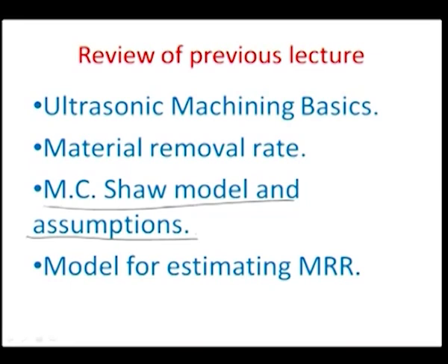And also that the indentation created by this grain would produce a crater on the surface, and for all practical purposes we should consider the amplitude of motion of the tool head to be constant, and so forth. So there were a set of assumptions that we had made for predicting the MRR or material removal rate, and then we started modeling to estimate what this MRR value would be.